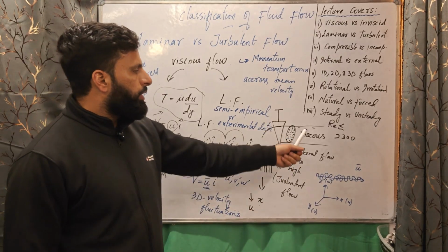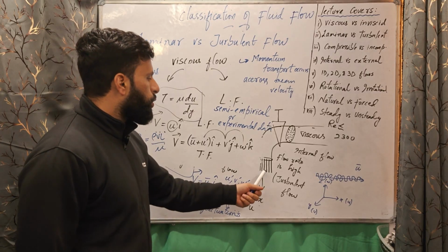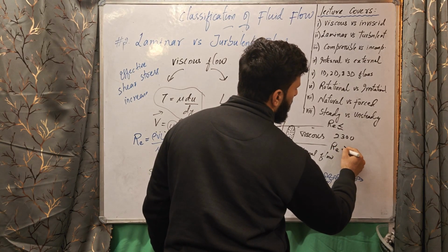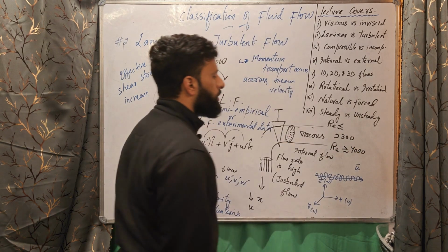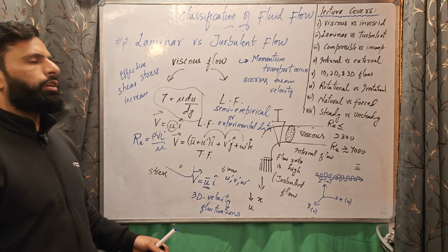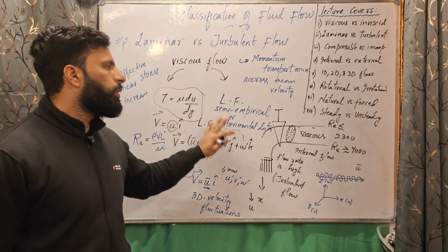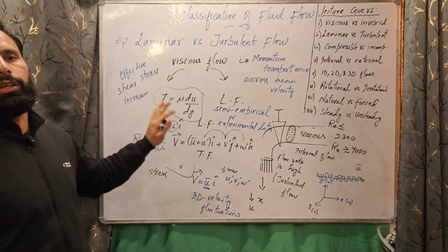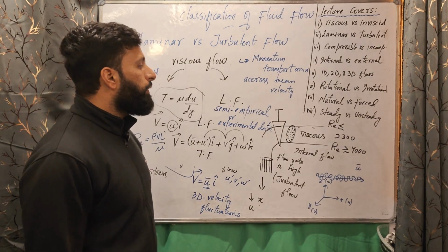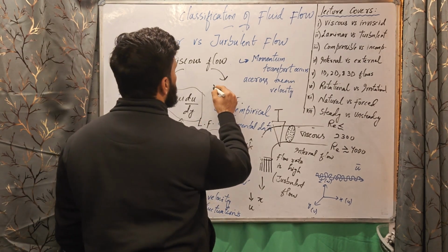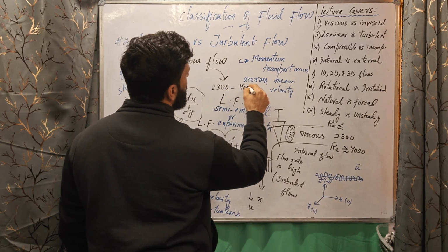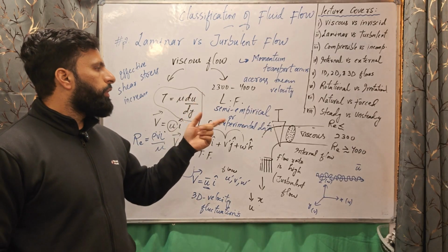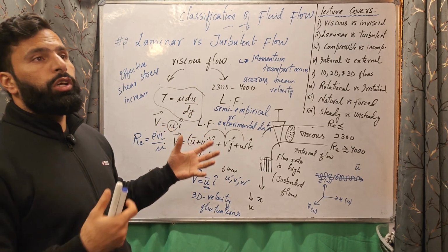the flow will be laminar. And if the Reynolds number is greater than 4000, it is regarded as fully turbulent, so we can study it using turbulent theory and turbulent data. If it is lesser than 2300, we use the laminar theory that we studied. And if the Reynolds number is between 2300 and 4000, this value gives us another flow regime.